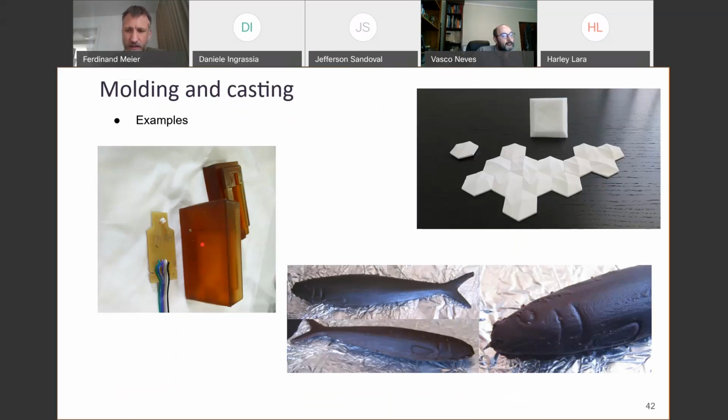Oh yeah, anything that you have inside your mold is going to want to swim up. So whatever piece you put into silicone or into casting resin, make sure that it can't move. Even if you put some force on it, it should be there solidly. This is another nice example for a coupon, which you can finish today.